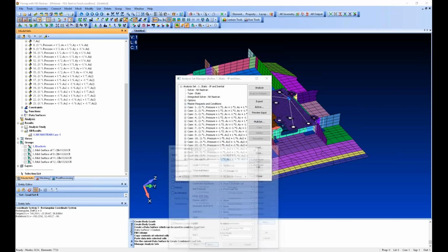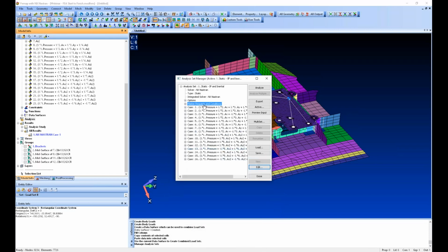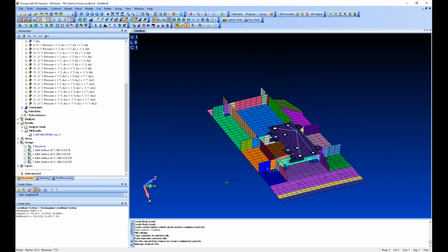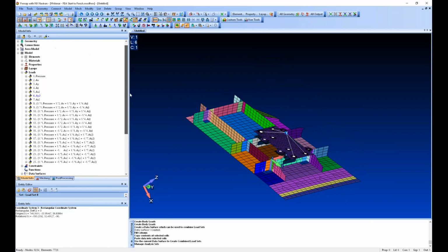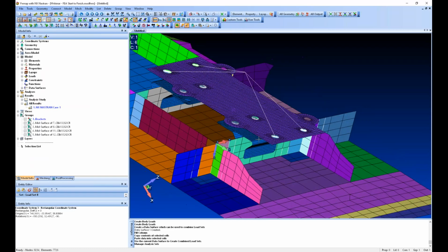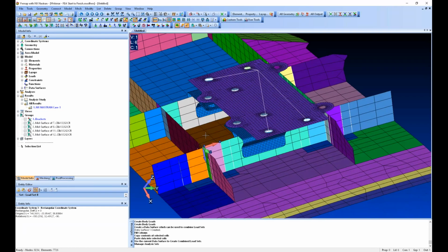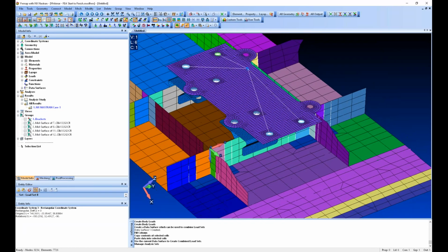I can specify the constraints as a master constraint set that get applied to all load cases. So that gives you the ability to specify different constraints for different load cases if you want. In our case, we have the same ones in all of them. And so that's our analysis is fully set up and ready to run. I'm not going to run it today because I didn't want to bore you by building too many rigid C-bush connections, so I don't have it fully connected up yet.